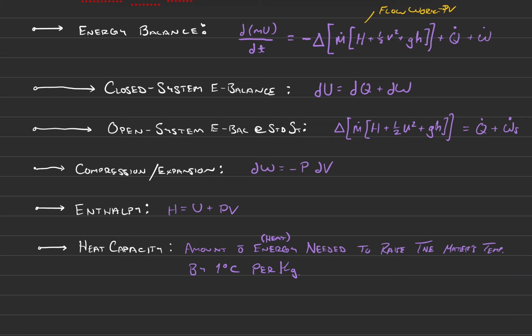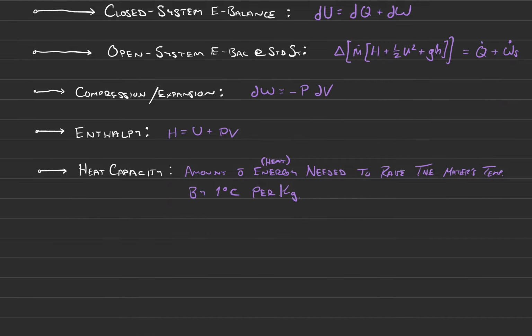And we talked about how in fluids there are two kinds of heat capacities that we were concerned with typically. So we have the constant volume heat capacity, right? And we said that definitionally the constant volume heat capacity is always going to be equal to the partial derivative of internal energy with respect to temperature at constant volume.